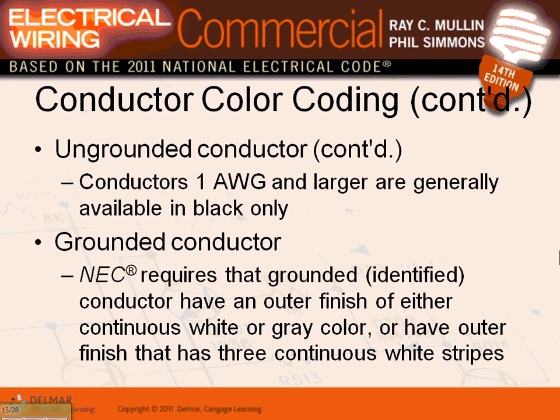But we have a lot of projects where the owner or the engineer specifies color-coded conductors for feeders. Now, had these been a number 6 or smaller, you have no choice. They have to be color-coded. Number 6 or smaller. Number 4 or larger, you can use one color. I can use blue, as a matter of fact, for everything. It doesn't even have to be black, as long as you identify the neutral and the ground. Any questions, guys, about this?